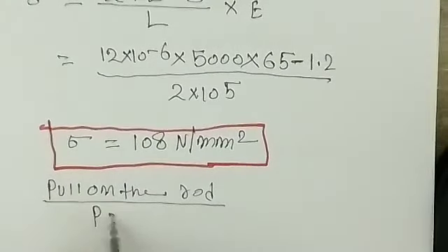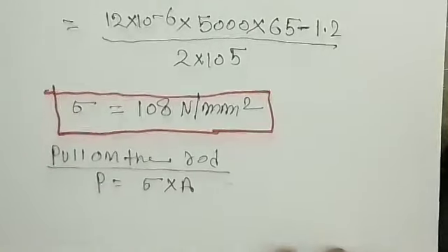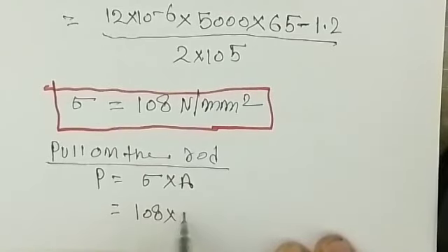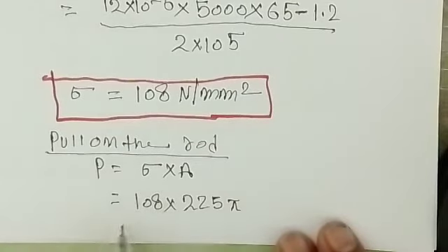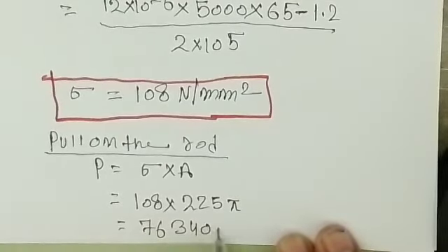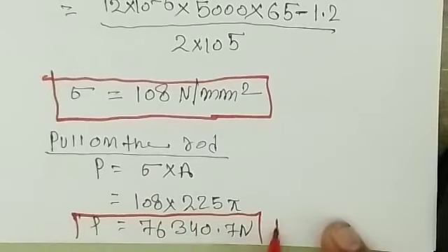Stress is 108 and the area we already calculated is 225 times pi, which gives 76340.7 Newton. This much of load we got.